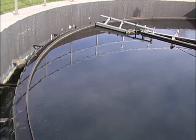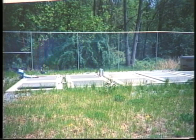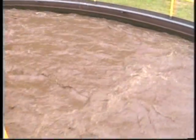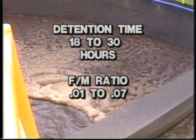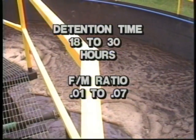After aeration, the flow passes into the secondary clarifier, where the hungry microorganisms settle out and are either returned or wasted. The extended aeration activated sludge process is most commonly associated with package plants. The configuration of the extended aeration system is similar to the conventional activated sludge plant, except the detention time in the aeration tank is 18 to 30 hours with an F to M ratio of 0.01 to 0.07.